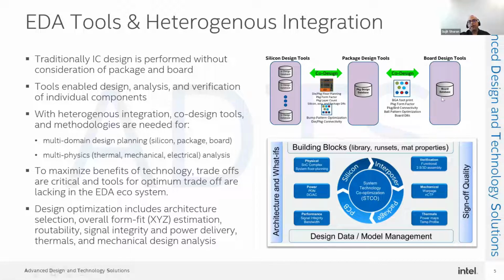And then on the other side of things, on the package side, the package designers work very closely with the board design teams to take a look at the board database, make sure that the BGA footprint or the LGA footprint is appropriately designed to, again, hit the right board layer count, board form factors, board connectivities, and optimize the performance across the entire stack.